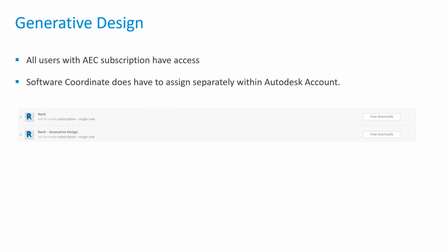Now, a little bit more information about generative design. So, all users that have an AEC subscription do have access to this. However, one thing that I do want to make you aware of is that every company's software coordinator does actually need to assign this separately within the Autodesk account. So you'll see a screenshot from my personal Autodesk account here on the screen. And as you see, Revit and generative design within Revit are actually 2 different entities. So just be aware of that when you're going and trying to assign this.